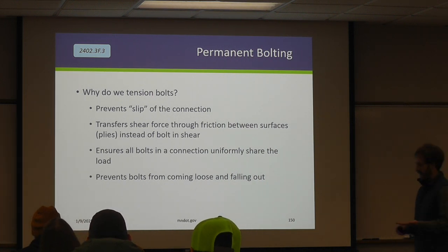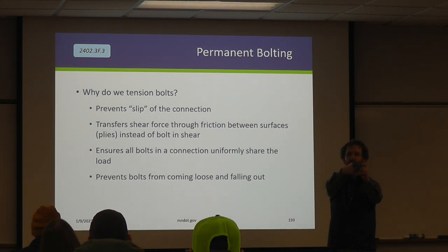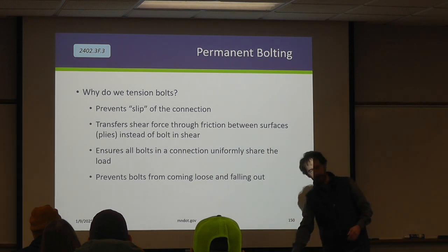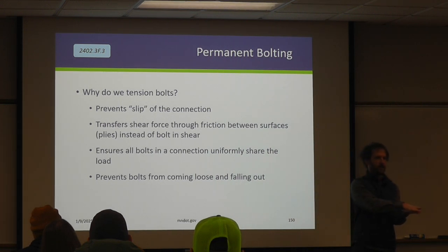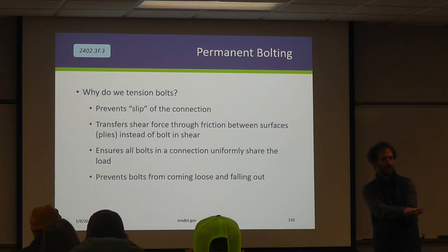These are designed, so usually we think about a bolt having steel bearing right against it, and that's what transfers the force. In a bridge, for serviceability and to give ourselves an additional factor of safety, we rely on the friction that happens between all of the plates. And in order for that friction to develop, the bolt has to tension it all into place. And that's a safety factor, right?